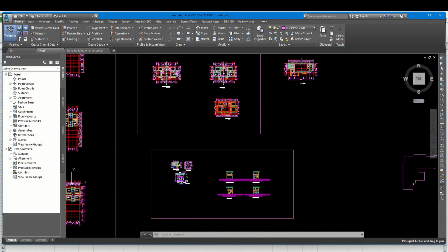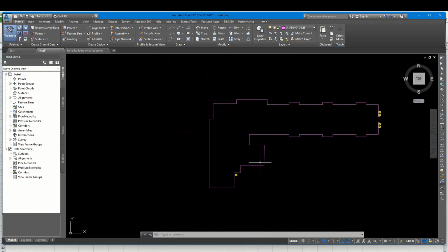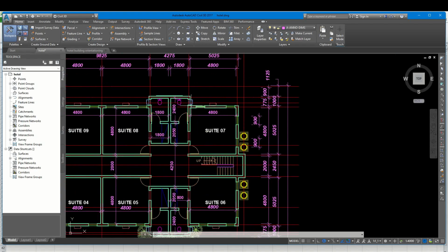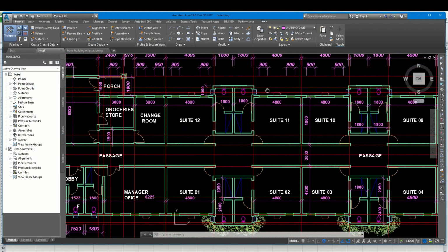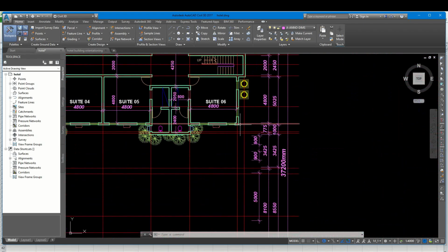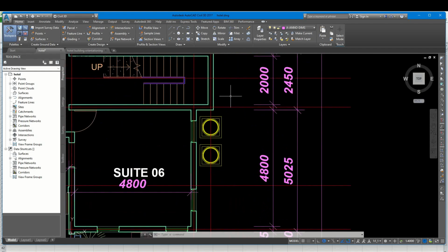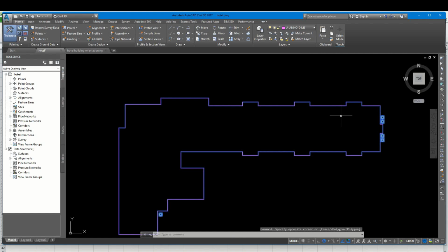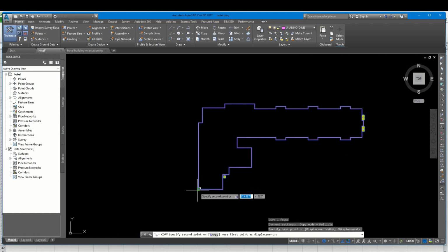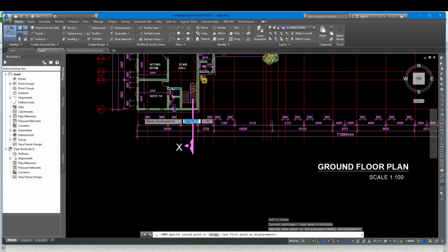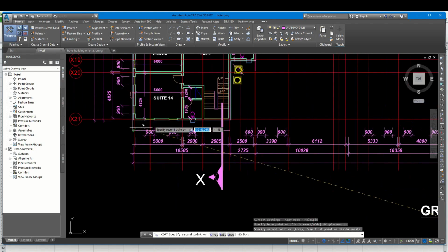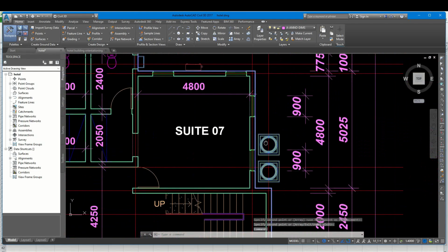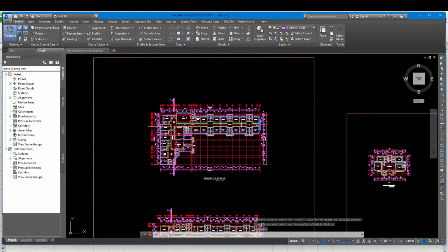Now I'll make my own block. I will use the polyline and go through the entire perimeter of the structure till it's close to the beginning point where you start, and I select the items of these pillars and make this a block. So if I should check this now that I have made, you will notice that it suits. There was never a shift. It should coincide to the entire perimeter of the building. So I'm okay with this one.